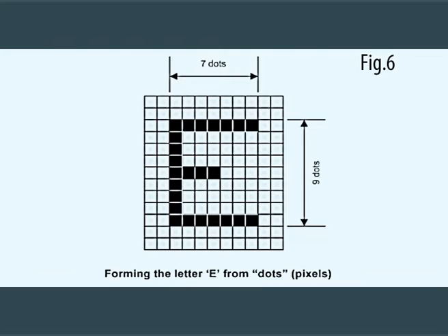Each character is drawn in a 7 by 9 matrix as shown in figure 6 below. Each row in above matrix is shown on one raster or scan line. So, it would take 9 scan lines to completely display a character. The character box is of bigger size, that is of 9 by 14 dots.